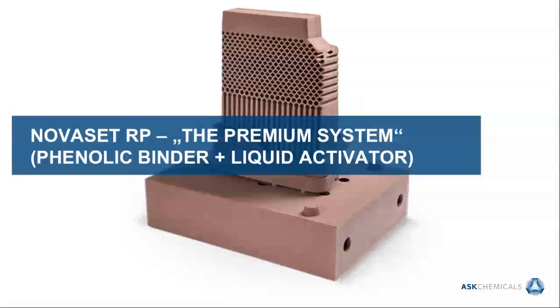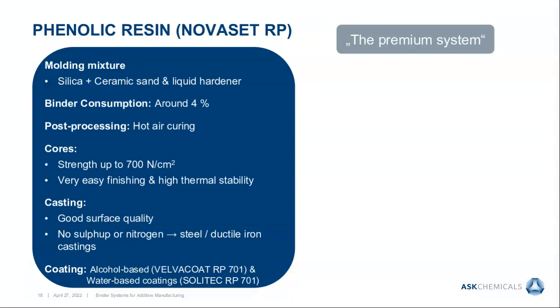Let's look at the phenolic binder system NovaSet RP, which is also combined with a liquid activator in the sand. And here the predominant sand systems are silica sand or synthetic or ceramic sand, and the liquid hardener is integrated into the sand.